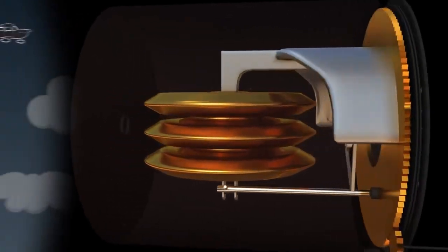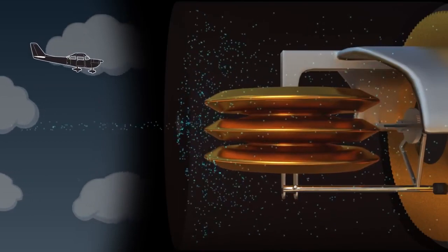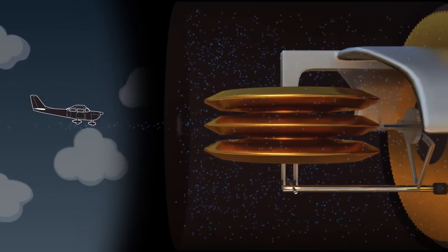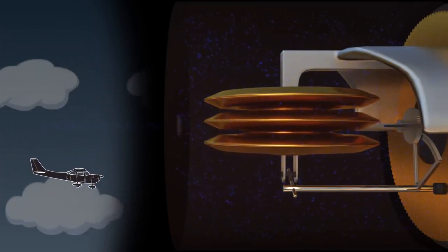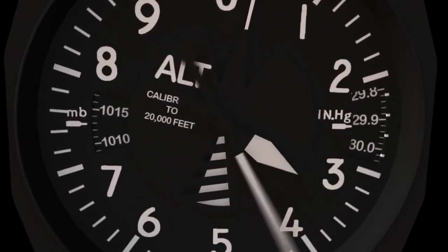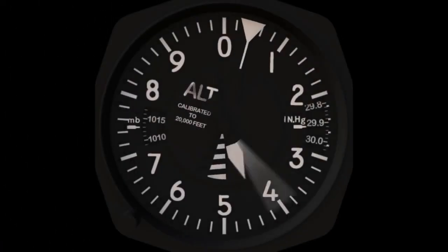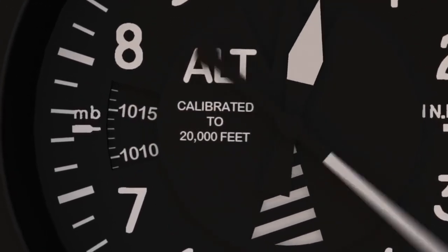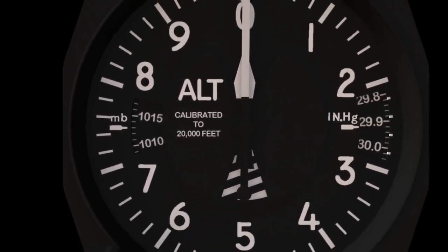Now, when the airplane descends, the opposite happens. Descending to a lower altitude results in higher static pressure. Air from the static port will now enter the case of the instrument and squeeze the aneroid wafers until both of the case pressure and the wafer pressures are equalized. The mechanical linkages will then rotate the hands on the face to show a lower altitude. The face of the altimeter contains three hands, the 10,000-foot, 1,000-foot, and 100-foot hands. These hands move clockwise and counterclockwise to display the appropriate altitude. Most altimeters in smaller aircraft will only work up to around 20,000 feet, but those airplanes usually can't get that high anyway.